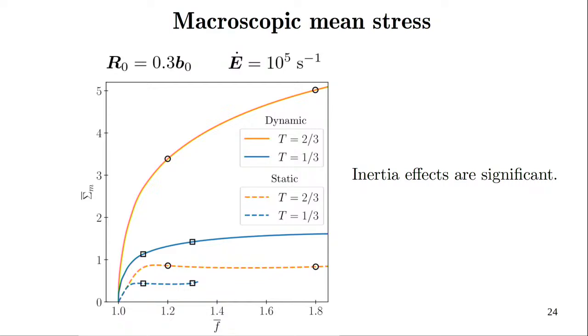So this is the response for uniaxial loading under static simulation, that is, inertia was off, and this is the response when the inertia is on under the same uniaxial loading. You can see the difference between the static response and the dynamic response. The whole difference is coming only because of inertia, because material rate dependence is already included in this part.